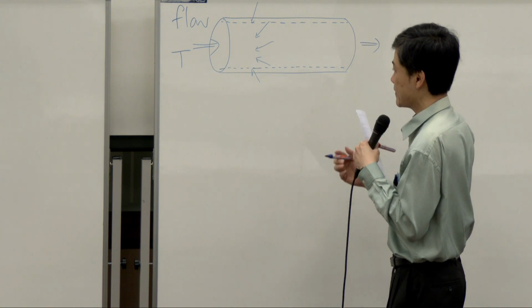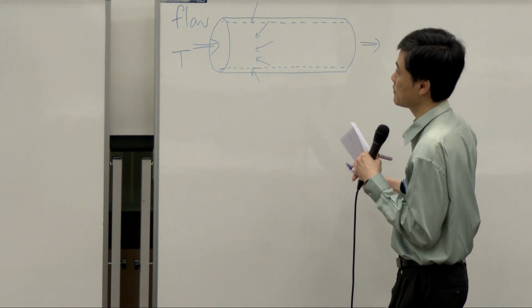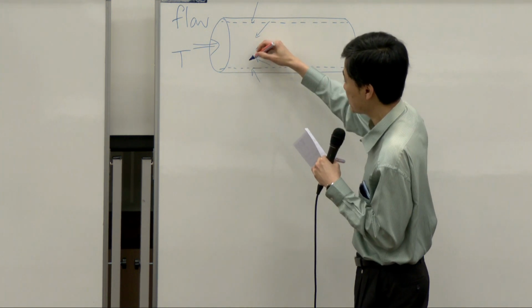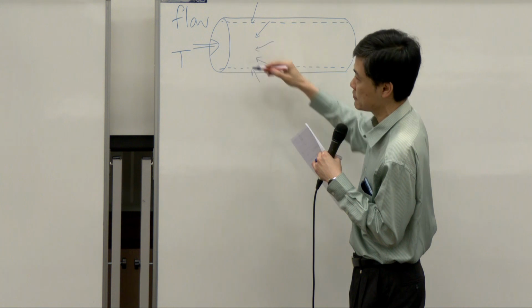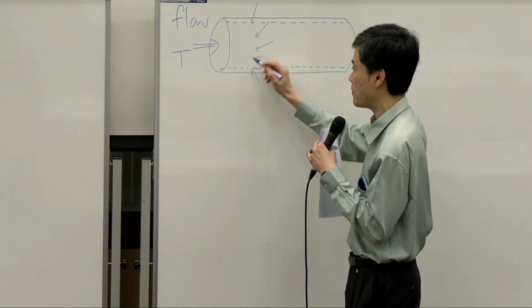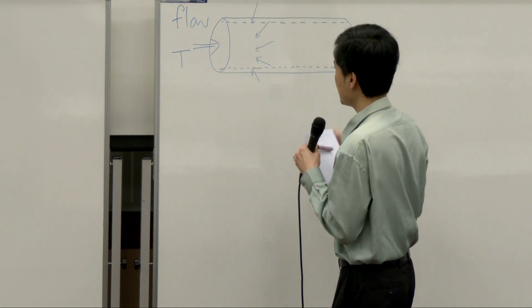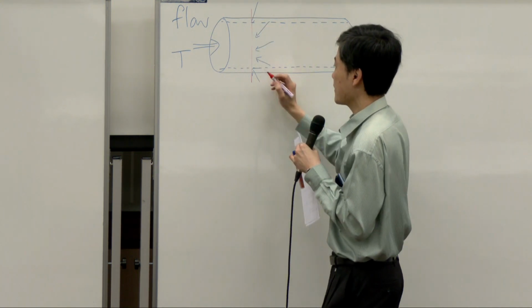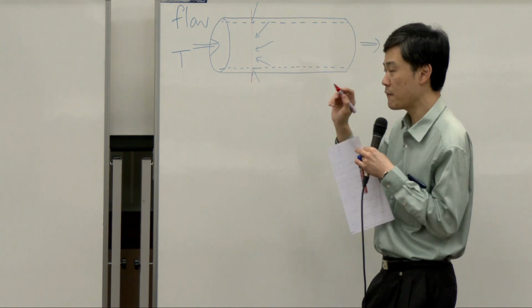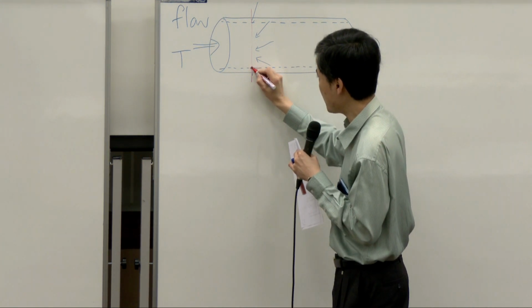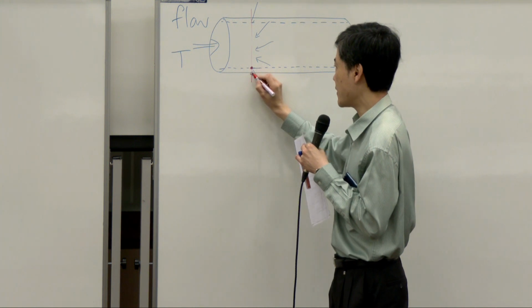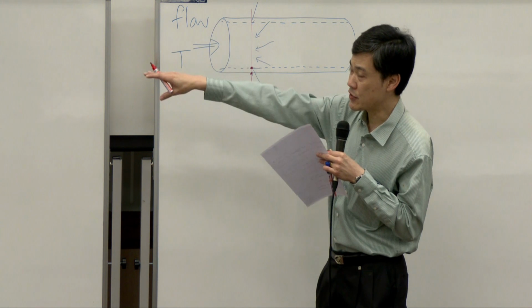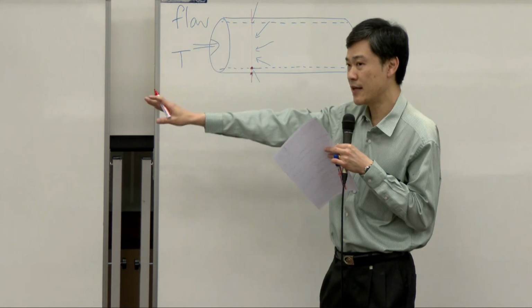So in this case, the driving force for heat transfer through this foam resistance is supposed to be temperature at the bulk or at the interface between bulk and foam. For instance, if I'm looking at this position, the actual driving force is supposed to be the difference between temperature at this point and temperature at the wall. All right, just like in that picture for the heated wall.